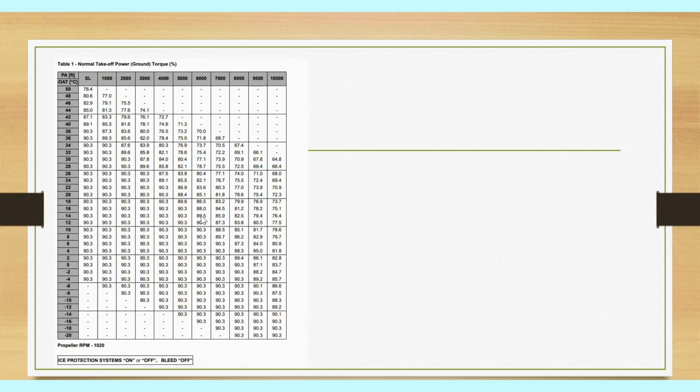Okay, now we want to find the end top torque. You see, that's how we compare. Remember, that's what we do to compare if we can reduce or not. So for our end top torque determination, first of all, look at the column which is relevant to us, which is the 5,000 foot column, which is the pressure altitude for Harare. There it is. Good. 36 degrees is exactly here. So this time is a proper value, no interpolation needed. And the end top torque is 75%.